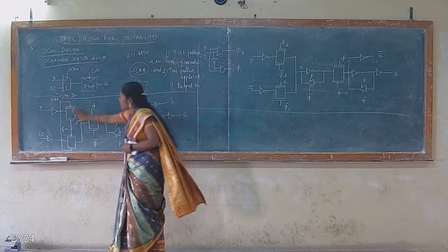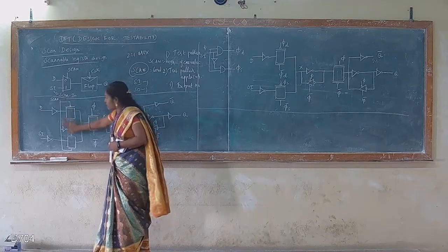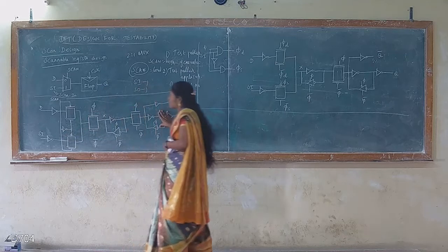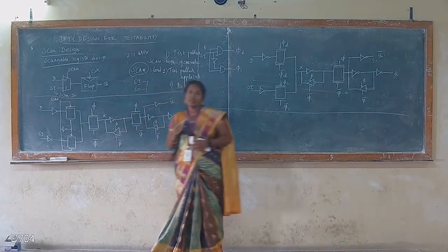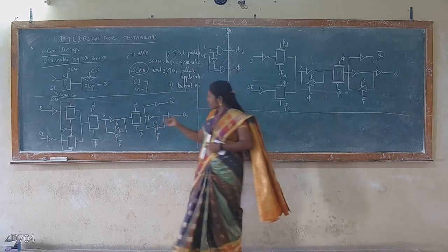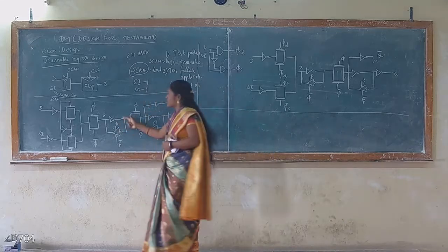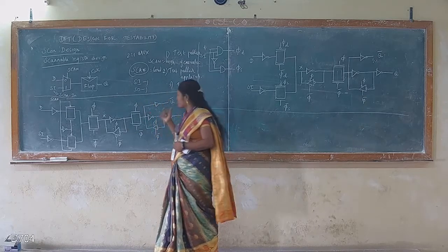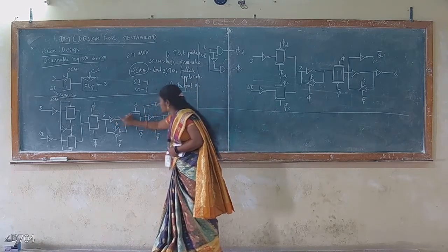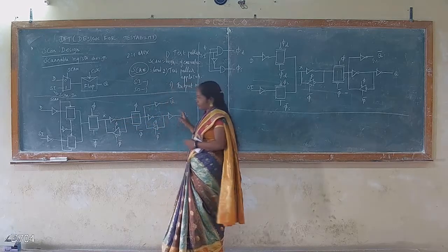So this is the implementation of the scan register, that is a multiplexer, and this is the implementation of an ordinary D flip-flop. Usually in the transmission gate implementation, at the input and output we are using inverters. That means we are isolating the output from the noise. So for that we have to connect inverters at the input side and the output side.